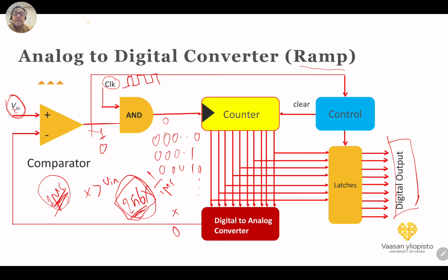So it is a very, very large bit rate or clock rate in order to convert within 1 microsecond. What if we want to have 10 bits accuracy? In the case of 10 bits it means more than 1000 counts. And if the sampling rate again is 1 microsecond, it means that the clock rate should be at least 1 gigabit per second. This is doable, but it is not simple, and it is not cheap, to build a circuit that can work at a clock rate of 1 giga or 10 gigabit per second.